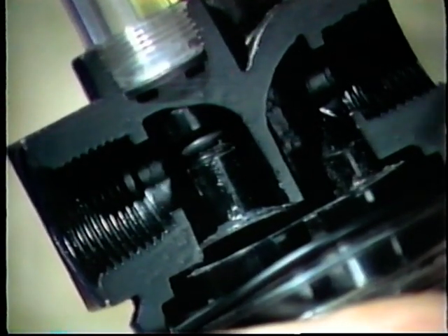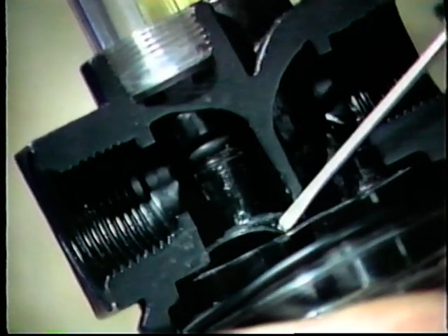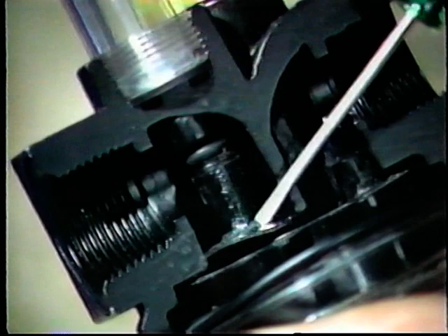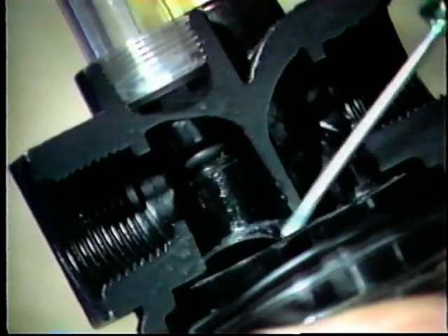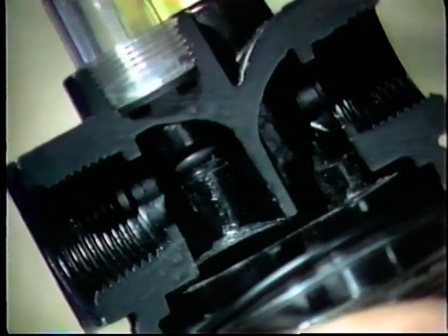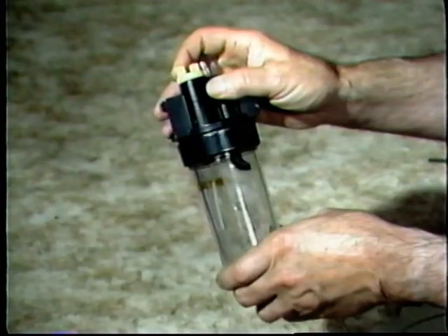At higher flow rates, this little rubber baffle bends down, so excess air bypasses the venturi section and blends with the venturi-produced oil-laden air at the lubricator output. Some lubricators do not have a blowback check valve built into them to prevent reverse flow from the bowl chamber. Therefore, it is good practice always to shut off the pressure before filling a lubricator.